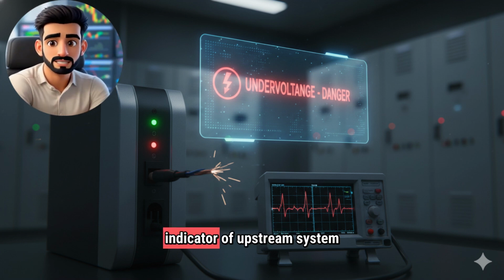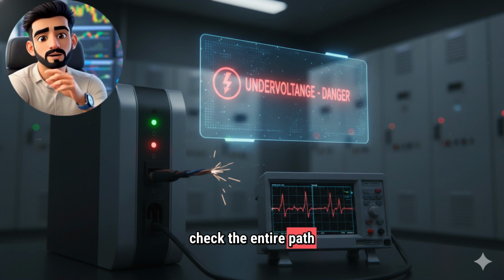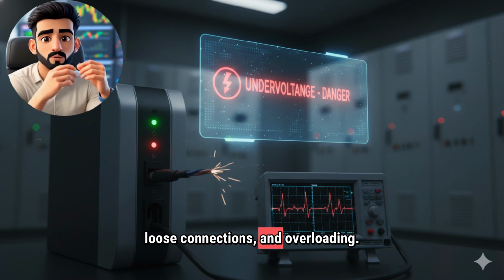Sometimes it is an indicator of upstream system health. Therefore, when an undervoltage fault occurs, you should check the entire path from the panel to the transformer. Verify voltage drops, cable heating, loose connections, and overloading.